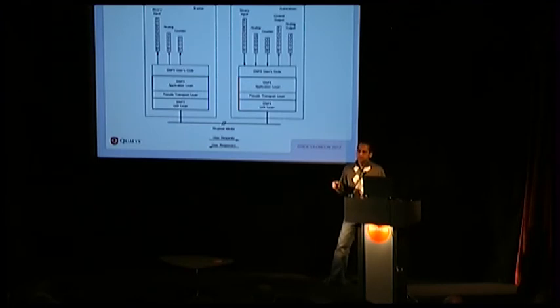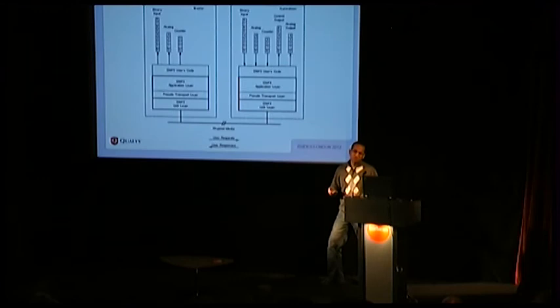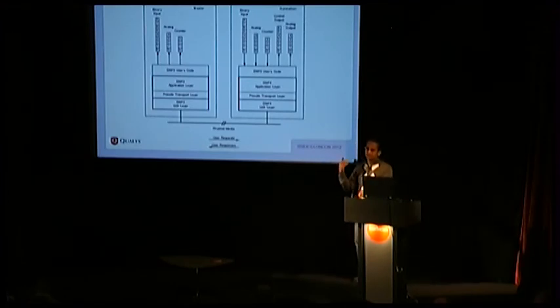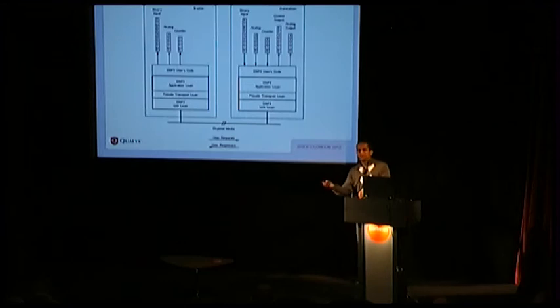In Modbus, when I make a request and receive a response with that transaction ID, I just have to assume that I made the request at about 4:15 and got the response, so the temperature must be at 4:15, but there is no real timestamping. The electrical system couldn't do without timestamping. So here the client sends a timestamp and the server sends a timestamp saying, you requested some electric reading, and this is the reading at this time. A lot of improvements in DNP3.